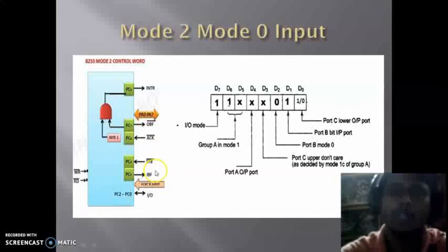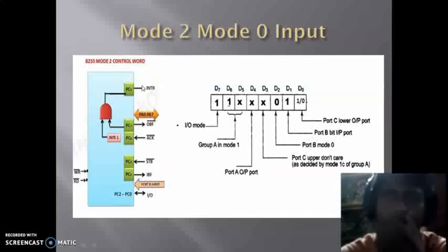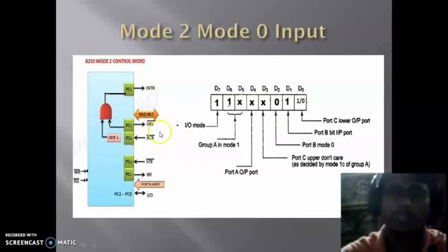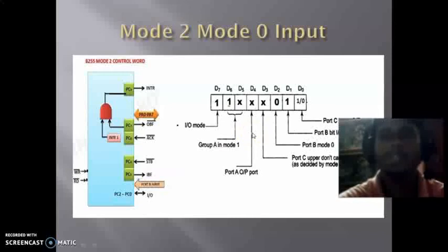Every time data goes in or out through port A, INTR is activated and sent to the microprocessor, telling it that data was received or sent by the 8255A.